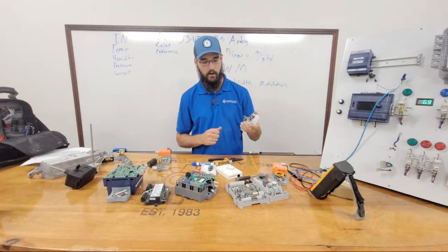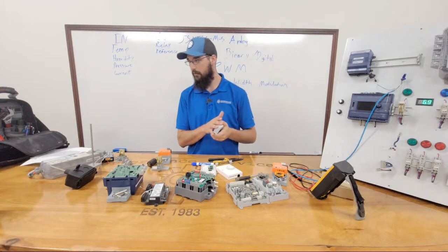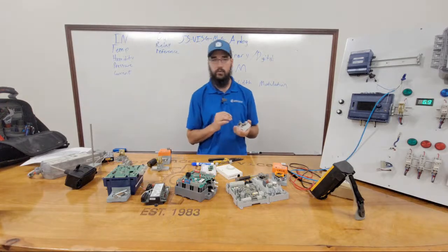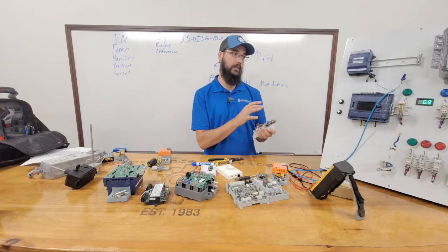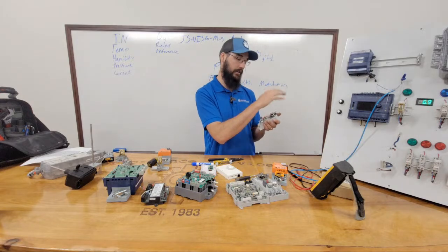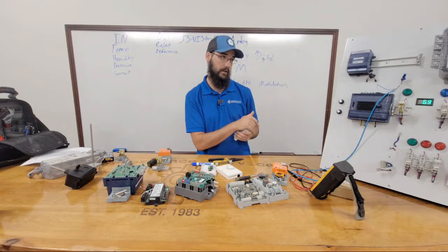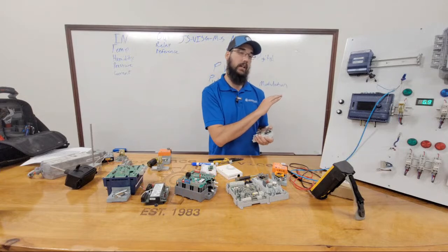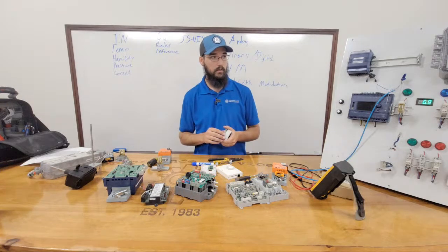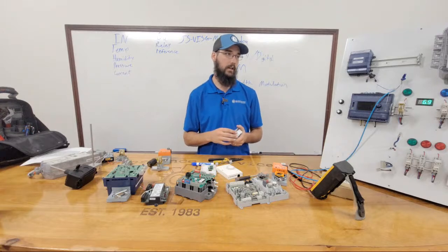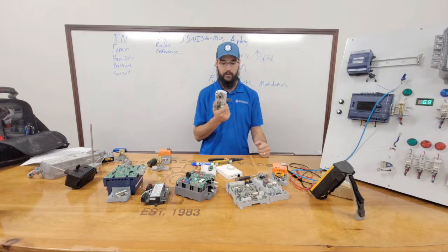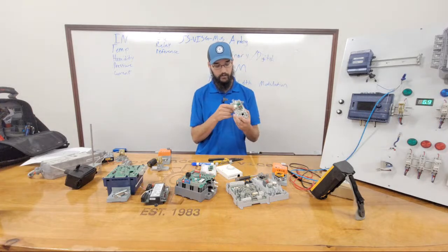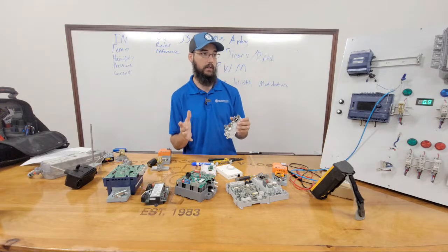If you have fairly open access to the automation system, you can just go in and override. So say it wants to be at 100, it thinks it's at 100, it's not at 100 though. Tell it to go to 0 and override it on the automation, and then just stand back, and you need to give that actuator the time that it actually needs to actuate fully.